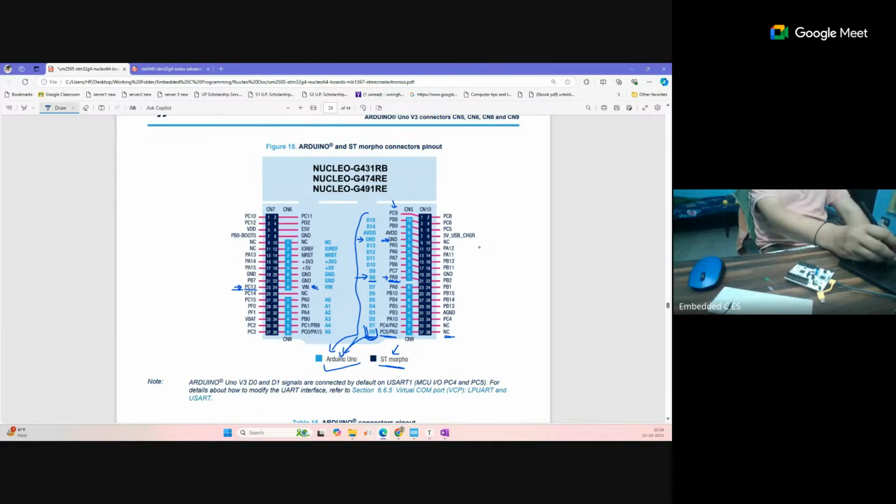But corresponding to that, our STM32 pins are also given. D15 is equivalent to PB8. PB means port B, pin 8. P means port, B is the port name, and then the pin number. In this way, we have these pins which represent the actual board pins.